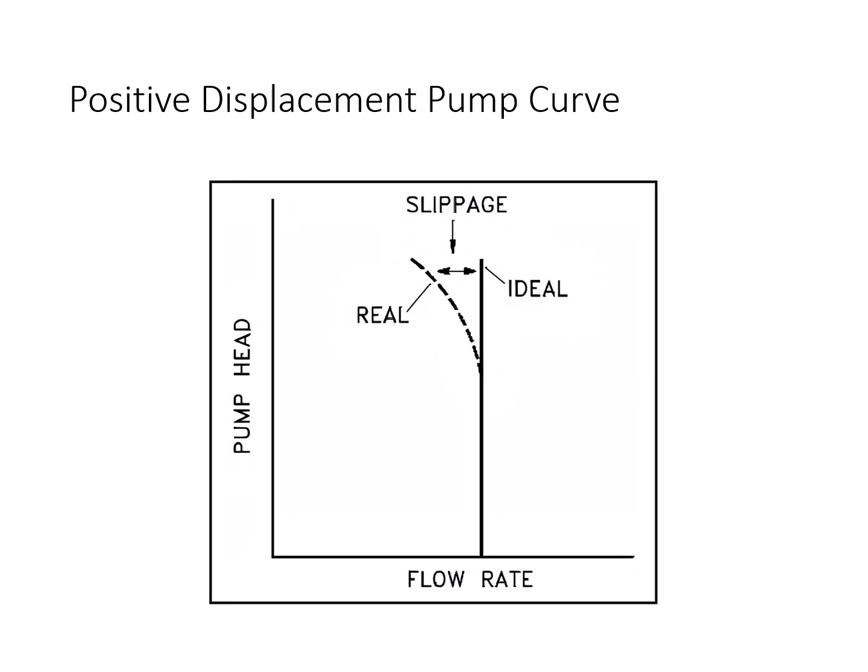If the system pressure increases, for example by closing a valve, the pressure output rises sharply, but flow stays almost the same unless the relief valve opens. So here again, the vertical line shows constant flow. If the line slopes slightly, like this, it is because of slip,